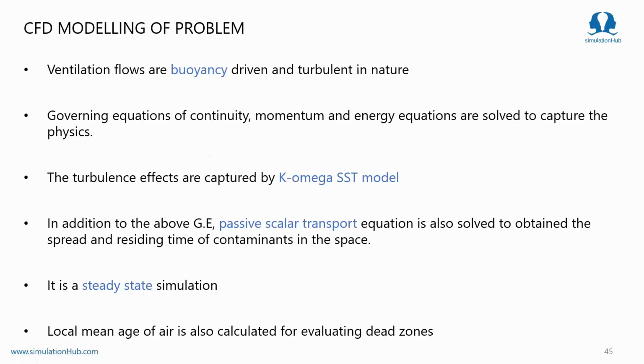Now let's summarize the CFD model. This is very similar to the CFD setup we considered for the isolation room. The only difference is that here it is a complete steady state simulation. In addition to that, we also perform the calculation of local mean age of air to assess the stagnant zone or any dead zone in the design.